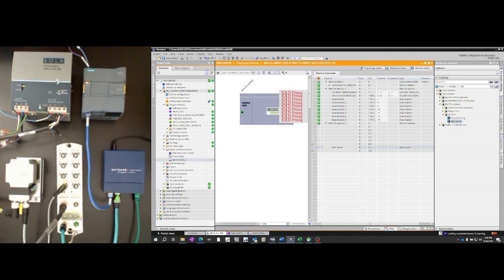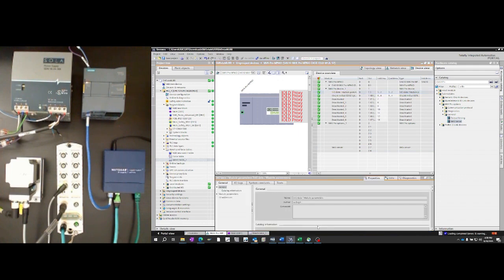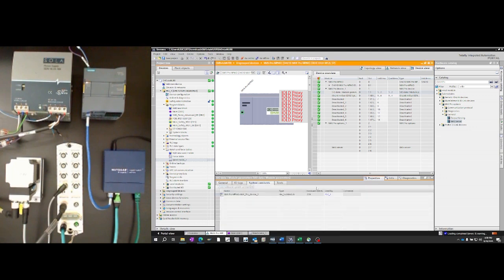So I'll open the device view, and if I want to communicate with all devices at all ports, I'll choose the IOLM or IO-Link Master proxy, available by clicking the SIO slot, pulling up the properties, and under System Constants, you'll see one hardware identifier, 278.